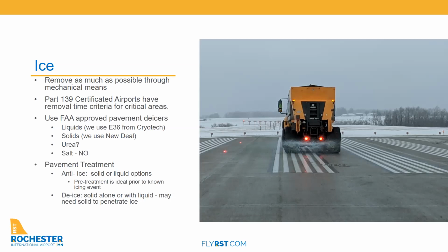So oftentimes during a freezing rain event, we'll continue to put chemical on there anytime that number dips off of 70. And so we'll never even hit 40. We feel that we use less chemical, we're staying ahead of it in that regard, and we provide a much better runway environment for the aircraft operators than if we let it get down to 40.